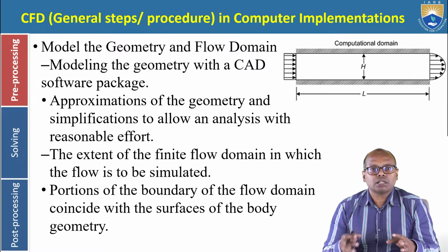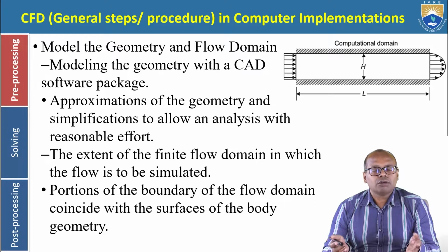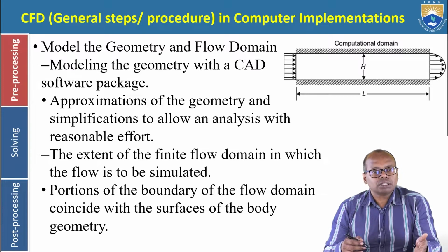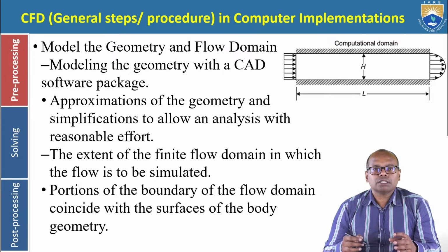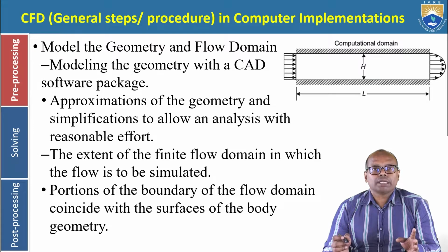All those things we have to finalize. Once we have finalized all those things and step on to the computer or the software, we have to perform these three steps. Now the first step is the modeling of the geometry or flow domain. So here in fluid flow or heat flow analysis, what we are interested in is the fluid.